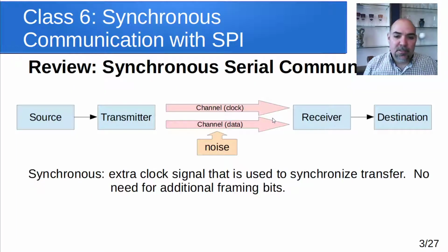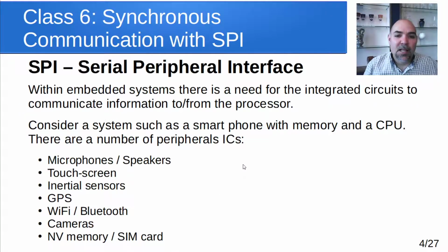Okay, so this is the idea, that extra clock signal being used. We've seen this before. No framing bits, just the clock signal. We're going to see that in SPI as well. All right, so let's dig into SPI and some of the specifics on that. SPI stands for Serial Peripheral Interface. So it's a serial communication technique. It's synchronous as well.